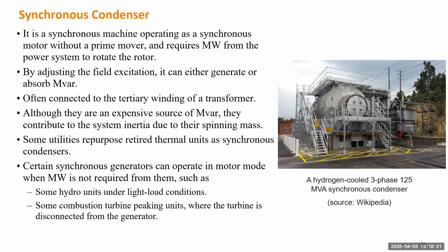So if you want to first verify whether the idea is good or not, to place the voltage controller there, one very easy method is just to place a synchronous condenser there. So in your model, if you decide you want to add some automatic voltage controller at those locations, but you want to verify whether those locations are good or bad, you can put the synchronous condenser there. Basically just a synchronous generator, but without prime mover. The input mechanical power will be 0, and output also 0.